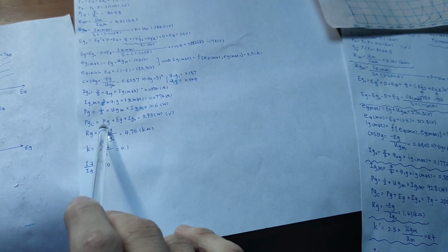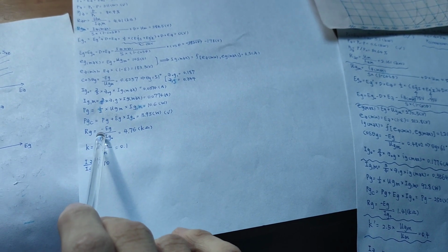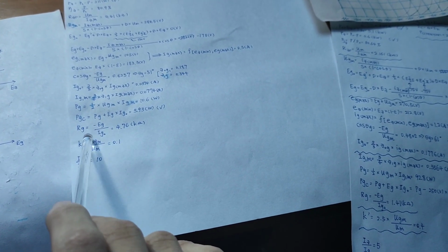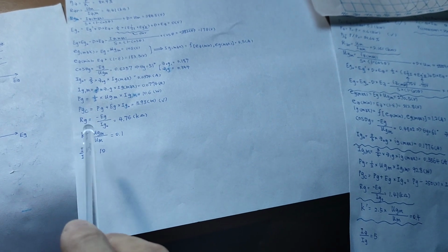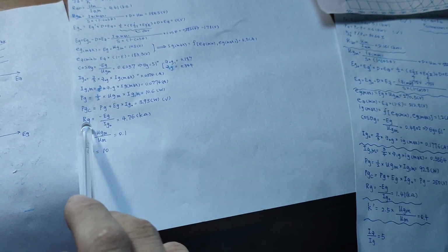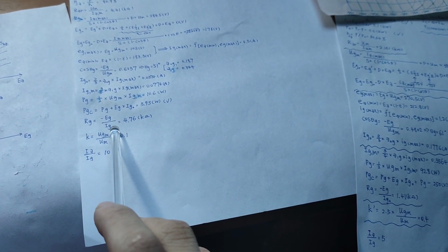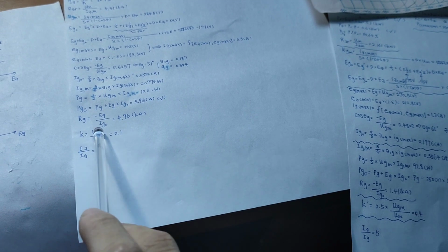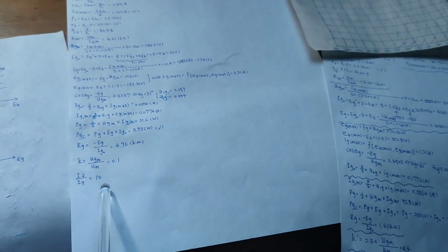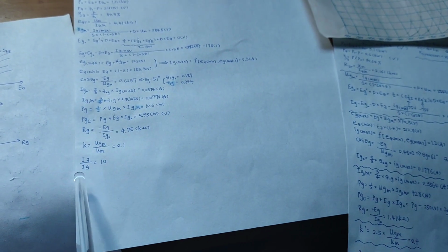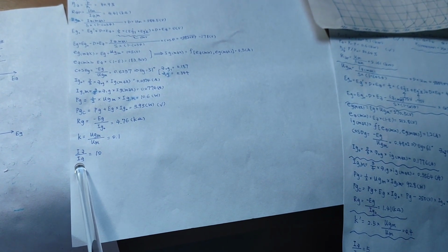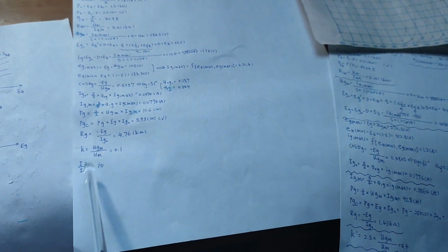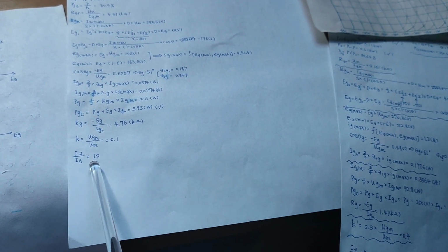Use the positive value, so you will add a minus here, right? And this is actually the feedback ratio, the minimum feedback ratio you need to get. Simply the maximum grid voltage divided by the maximum anode voltage. In this situation, it's 0.1, and I suggest you calculate this: the anode DC current divided by the grid DC current. By calculating this value, it will be easier for you to tune your oscillator.